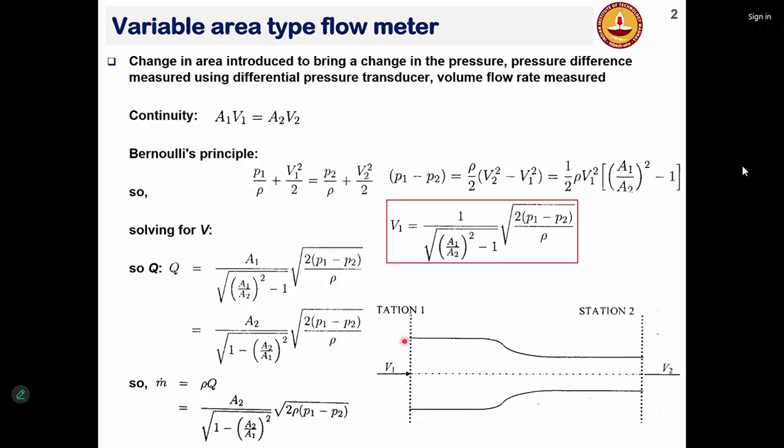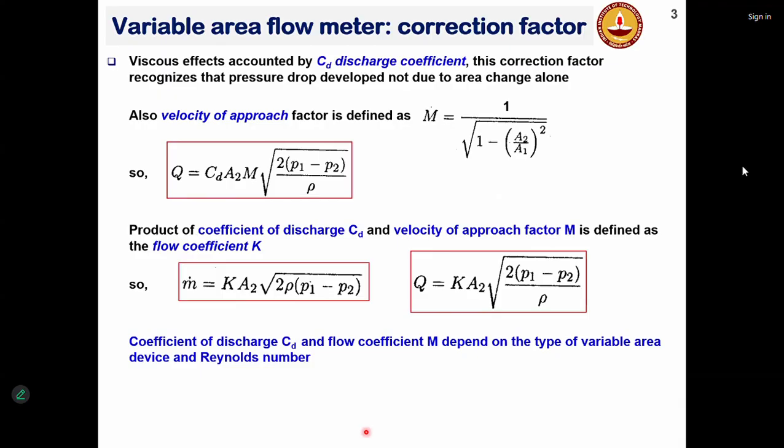But here, you are going to have a variable area so that the delta P here is more significant than the losses that are happening at the ends. Okay. Noted. So that is why you use this kind of variable area flow meter.